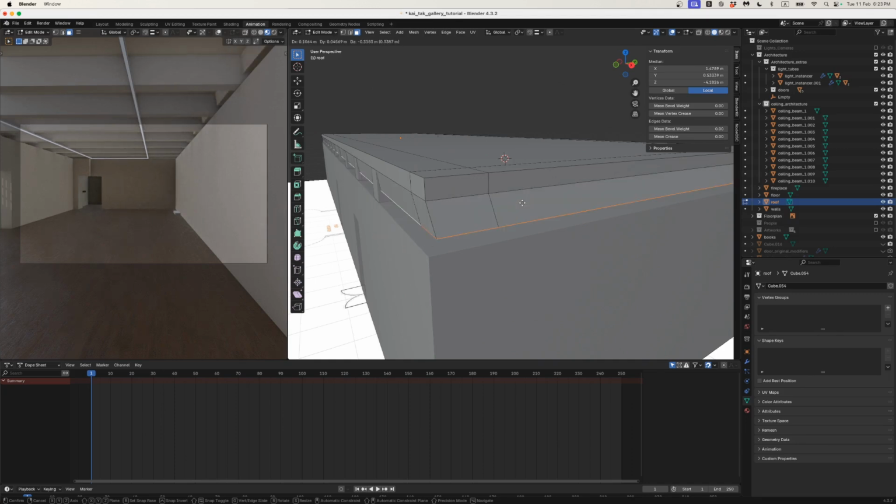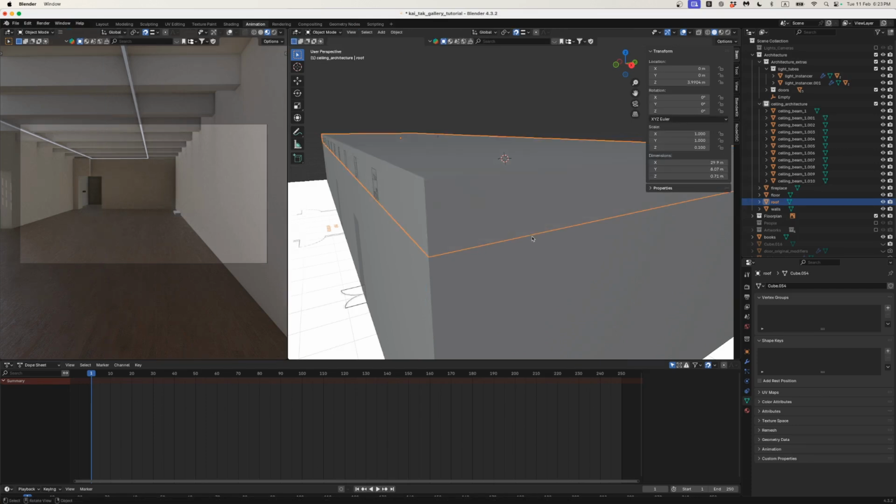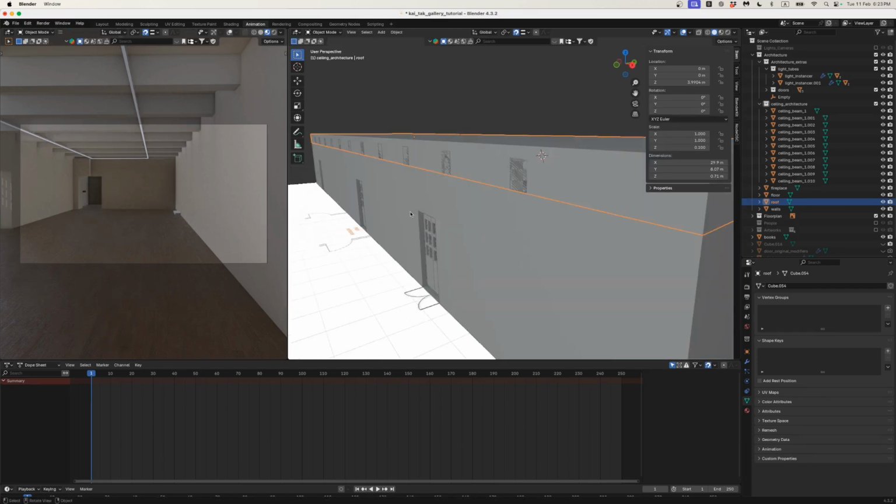And here that Z command hasn't registered, so I'm just going to press Z again to make sure I'm only snapping on one axis. Z, and then I'm just going to turn on my snapping, GZ, bring that down. Now that's closed things off, but we've got this overlapping geometry here with our pillars, or our beams.